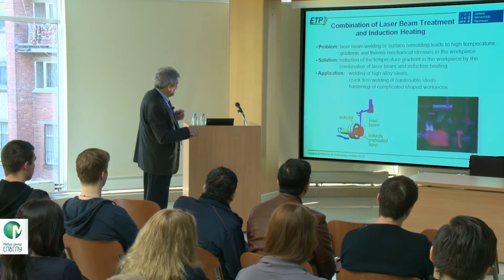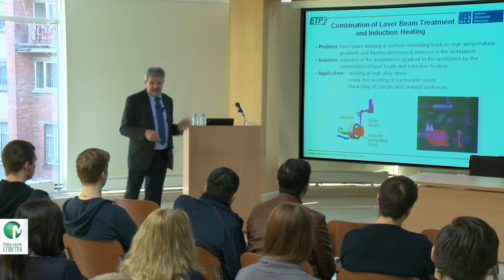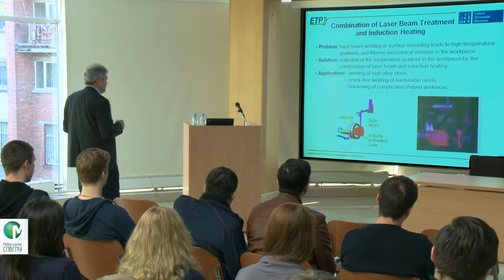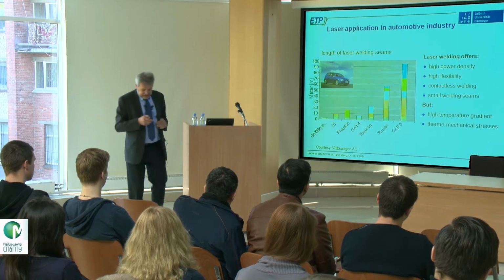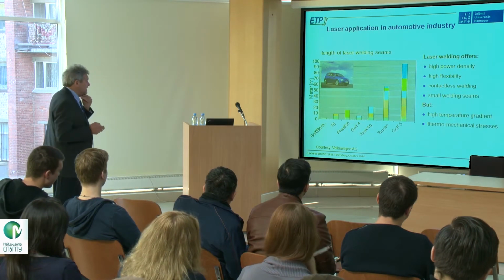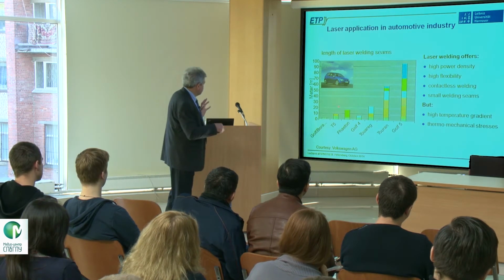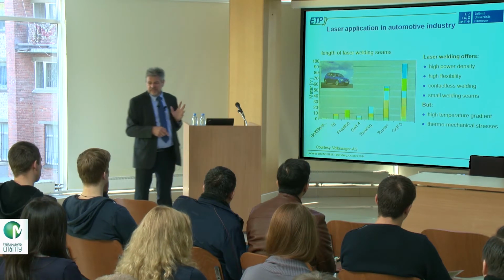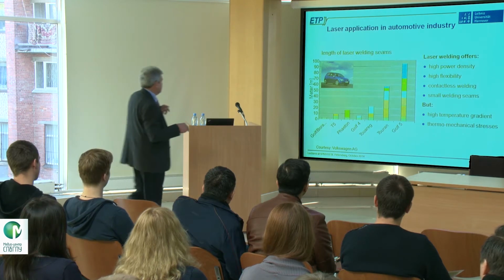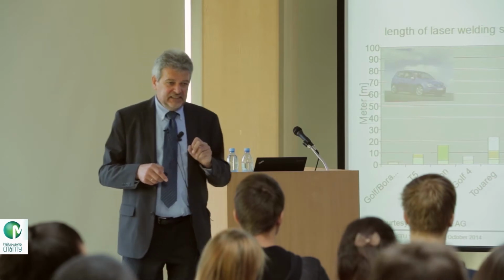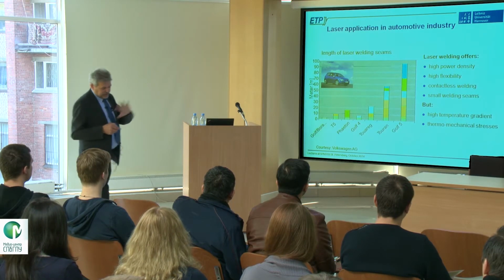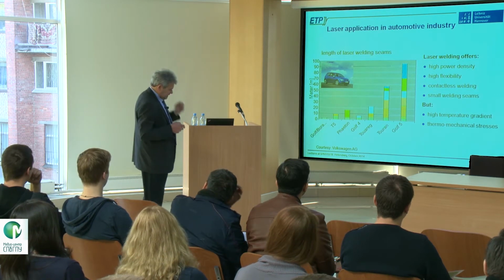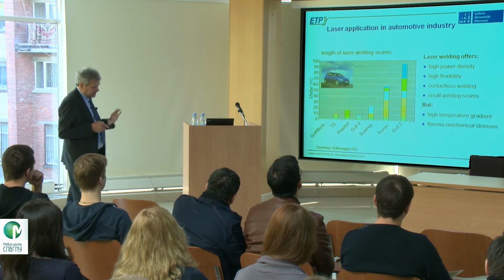Here's a general sketch, laser welding and then treatment by inductor, but this was drawn by somebody who was not very familiar with induction heating, so it's not so easy like described here. It was only for advertisement. So, some short words on laser applications in the automotive industry. Here you see an example of Volkswagen, how many meters are welded by laser. Today we have Golf 6 or 7 already, this was already 5. Already nearly 100 meters were welded by laser, because it gives a lot of advantages compared to classical welding of car bodies: less mechanical treatment and tooling afterwards, better surfaces, and no problems with the lacquer and so on.